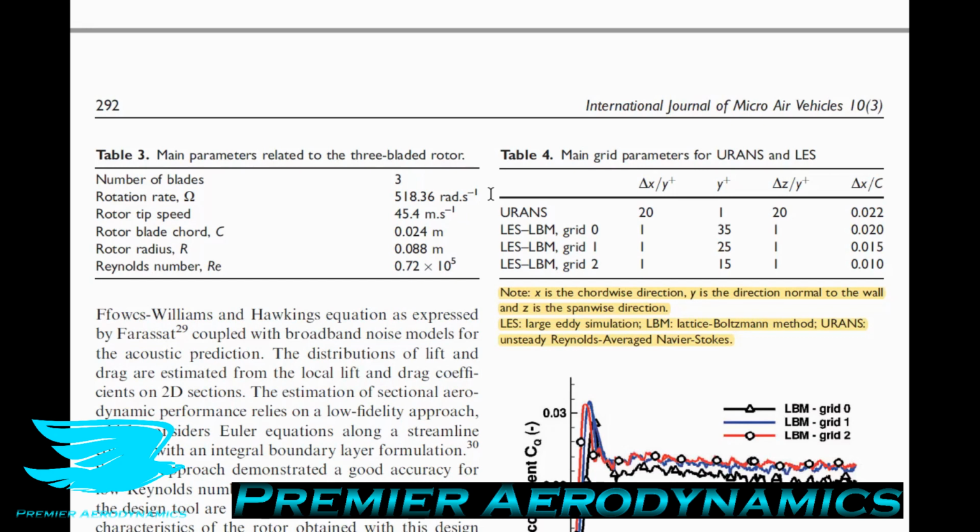If you want to mesh them properly, you then need to make the entire domain that high resolution. Whereas for Navier-Stokes CFD, you can put in little regions where you resolve more finely, more detail. So that's the problem with LBMs at the moment, which is being solved in some packages.